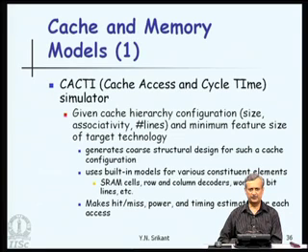In other words, there is a library already available for each type of technology, that is for SRAM cells, row and column decoders, word and bit lines, registers and so on. So, with all these various buffer registers, it knows exactly how to put these things together to achieve the cache configuration that the user has mentioned, and thereby it synthesizes a structural design. It makes estimates of hit, miss, power and timing requirements for each access,